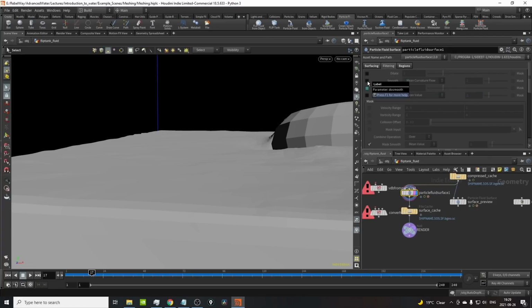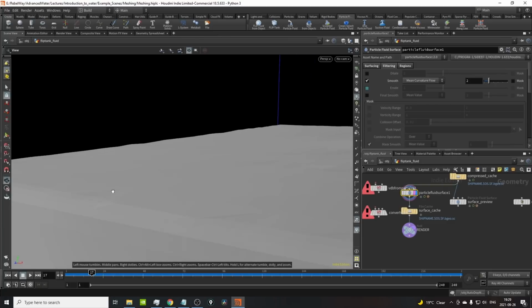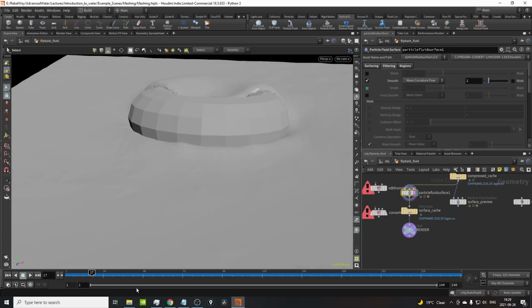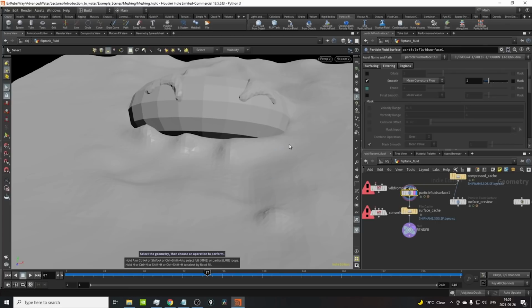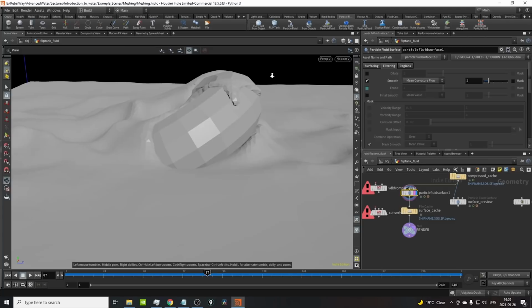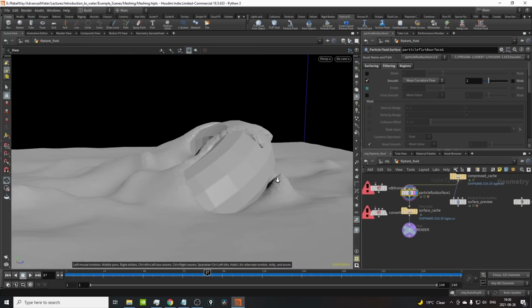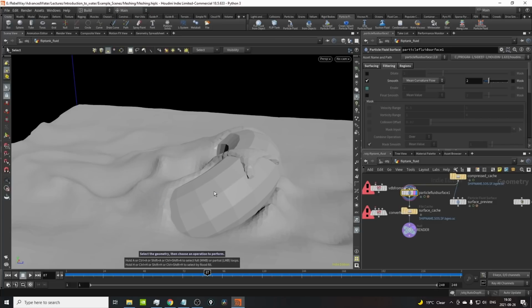And the way that is done is using filtering. So the easiest way is to just turn on the smooth and boom, right? We removed a bunch of the lumps. Easy peasy. The problem is, if we step a little bit further in here, we probably also remove a little bit of our simulation, right? It shrinks and we're removing these top peaks. We're blurring everything because that's all a smooth is, right? It just blurs and averages things together. And we don't want to do that everywhere.